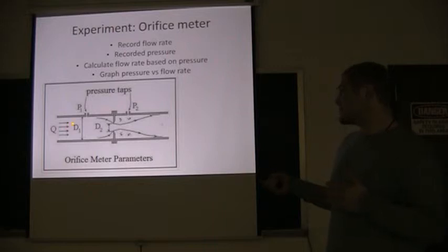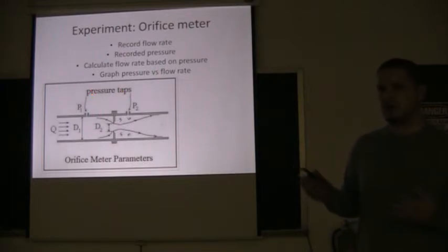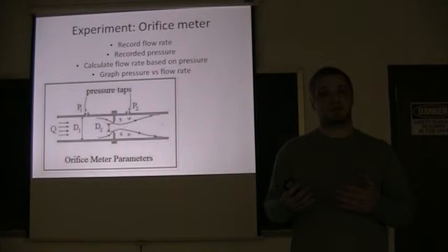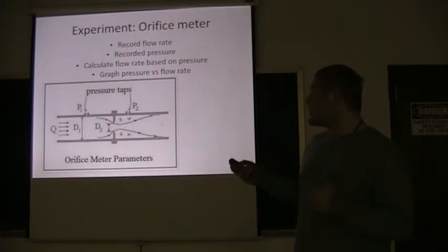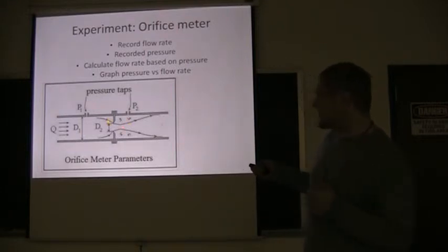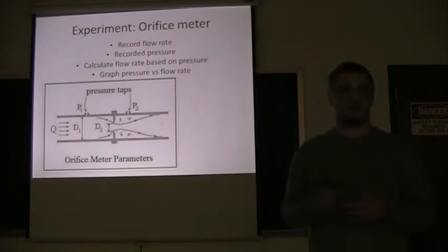So if you take the pressure of one, normally there's going to be a transducer up on top. It doesn't show it right here. It'd be a transducer or a manometer tube, something like that, to measure the difference in pressures. There are different ways of doing this in industry that help cut down on the pressure loss and all the currents that are generated because of this. Generally a Venturi tube or something like that, but for this experiment we have the orifice tube.